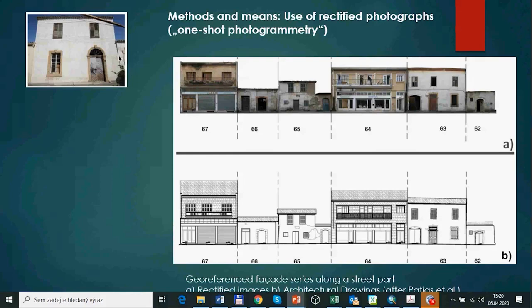The basic principle is that you take a good, clear photograph of the facade, which should be plain, without any conspicuous recesses or protrusions. So the facade should be plain, and you have to make control points on the facade before taking the picture. There are several methods for how to fix the points on facades. We can skip this problem, but it's not very difficult. You can use easy basic measurement methods, or use, for example, a total station. And then you take the picture.